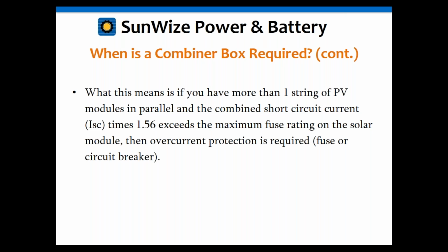And getting back to those little interconnects, basically what that means is that that module is rated for maximum current, otherwise those interconnects will fail. So you end up using those as your fuse, which is not a good idea. You can have a hot spot possible, and that hot spot could get hot enough to cause flames, which is an issue. So for safety reasons, you want to make certain you adhere to that maximum fuse rating that is on the module spec sheet.